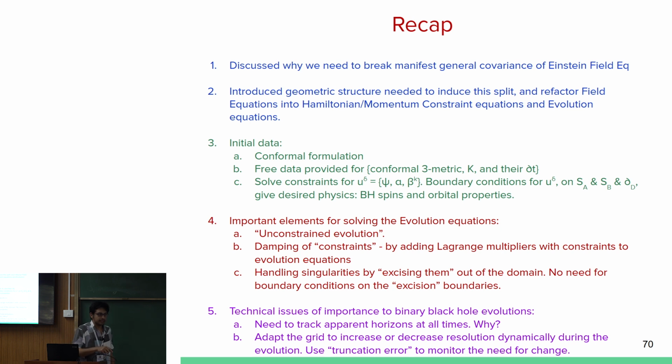So typically, it should be short, not too short. It should say of the order of 10 time steps that your solver is anyway taking. It should not be so short that you introduce a new time scale into the problem. That's all I'm saying. It should not be too short.